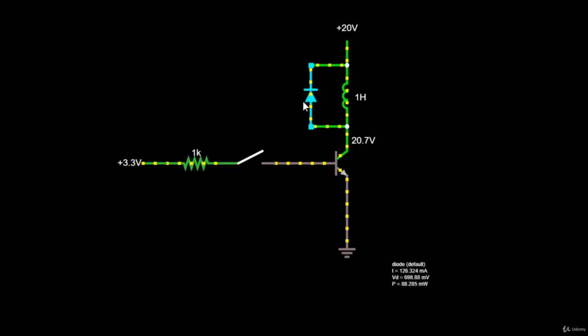What's important to remember is that the diode is connected in reverse bias when the switch is closed, and as a result, the diode doesn't impact the operation of the rest of the circuit when the motor is spinning. But when the switch is opened, the change in polarity of the inductor will place the diode in forward bias. So when the switch is open, the inductor will reverse its polarity and the diode will be forward biased. While forward biased, the diode will allow current to flow through and dissipate at the rate the inductor wants.